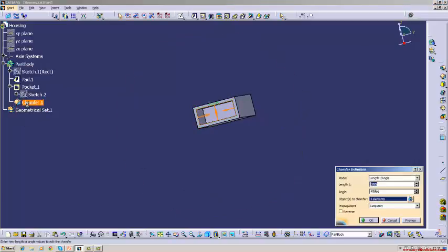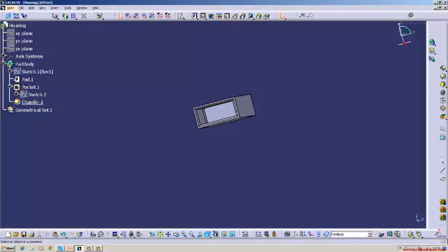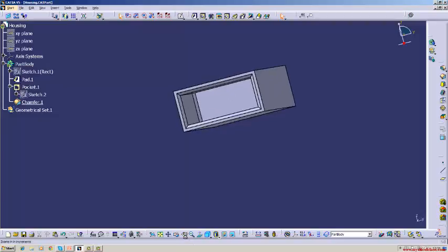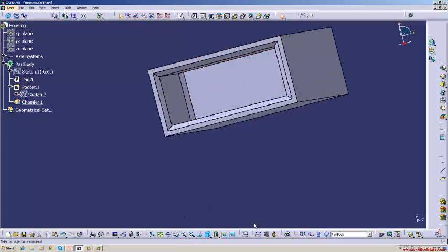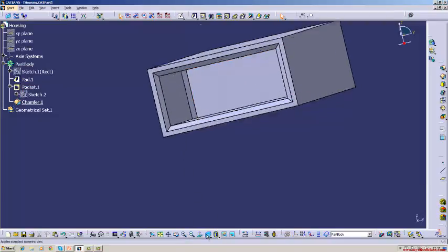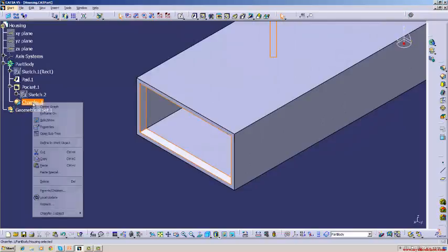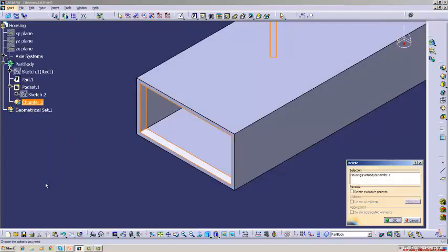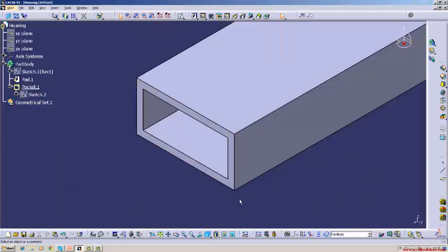You want to add inside, here parting line you have to add. See, inside chamfer is done. This side, all the sides. Whatever side you need, you can chamfer it. I will remove the chamfer now. Okay. And similarly, you can add fillet.